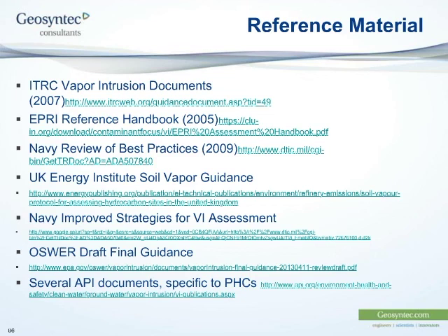Well, certainly moisture has a huge effect. Vapors can only diffuse through the air-filled pores in soil, and as the soil gets wetter and wetter, those vapors dissolve into the moisture and are diffusing through water. The aqueous diffusion coefficients are about 10,000 times lower than the gas-based diffusion coefficients, so there's a dramatic drop in the rate of transport in wet soils.